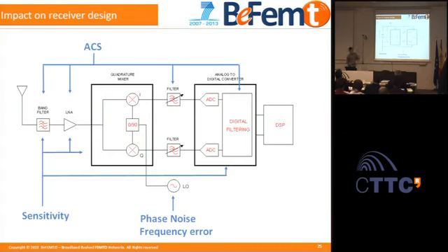In this receiver, we can see the band filter that rejects all interference and non-desired signals from other services. The low noise amplifier has a lot of responsibility for the sensitivity of the receiver. Then the quadrature mixer, the filter and stages for the baseband, and the analog to digital converter. It has also been represented which are the main parameters and which module is responsible for each one.